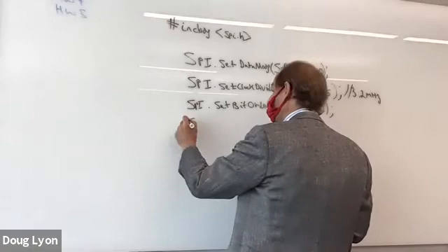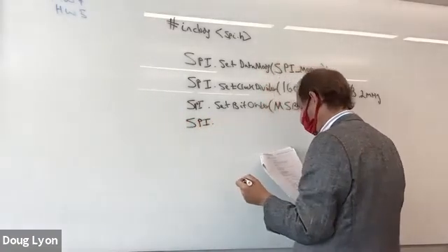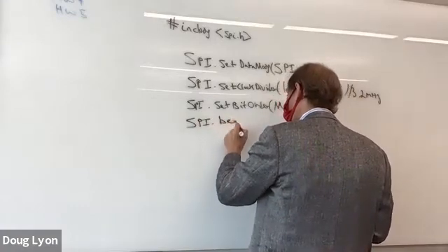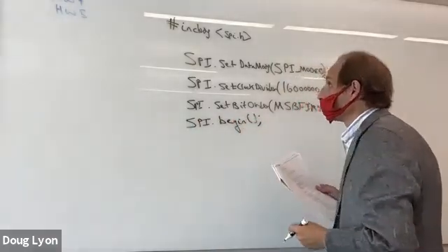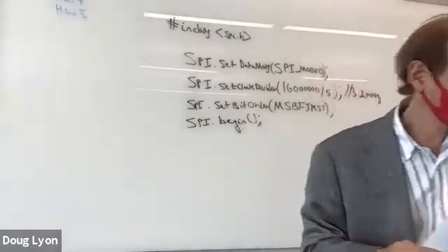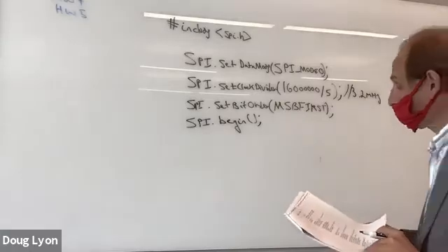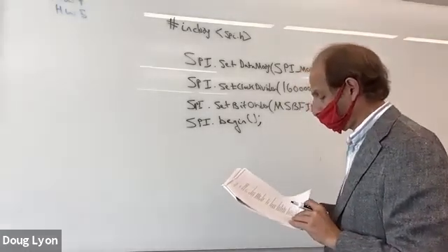The other thing you do once you set this up, this is just like setting up a serial port. And you could do this in the setup. Let's do a SPI.begin, just like the serial port. So when you're doing programming at the low level, you need to do the MOSI and the MISO outputs and inputs, but you have to establish the serial clock. And that serial clock is the clock that is used for communicating with the serial peripheral interface device.